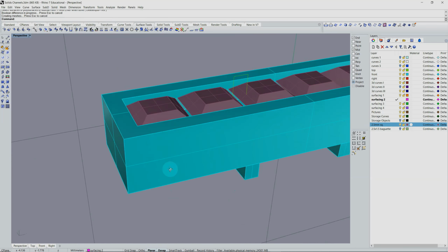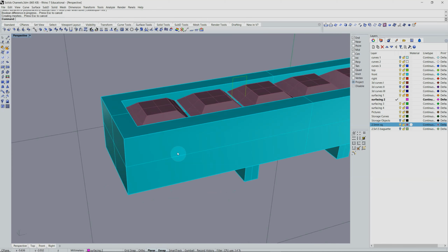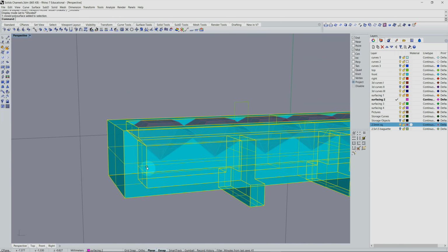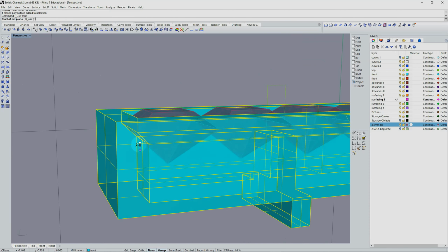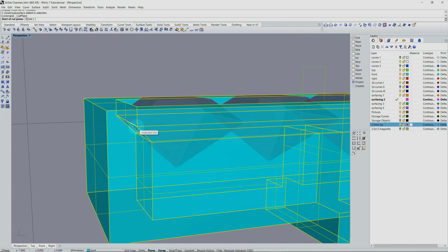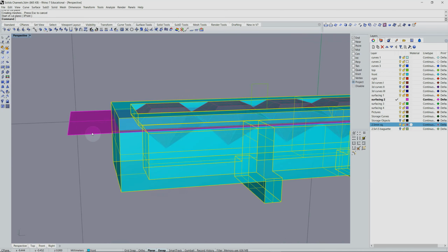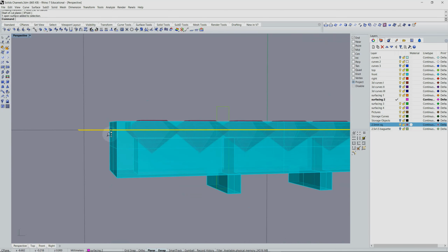I want to clip the bottom of this setting exactly 2 millimeters below the girdles of the stones. So, to establish my cutting plane, I'm going to pre-select my block. I'm going to select the cutting plane command off the Surface Tools tab, and I'm going to snap to the internal girdle level of my setting. I'm going to pull straight out with the shift key and click. This is the starting level of my cutting plane.